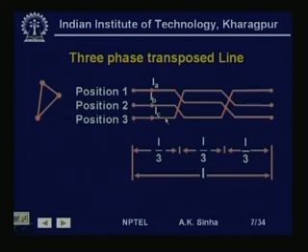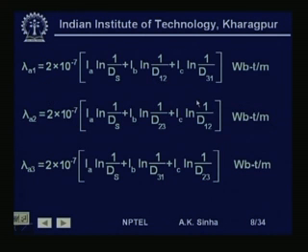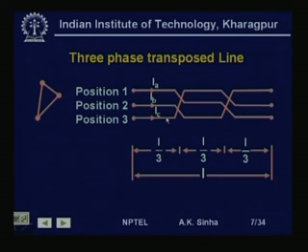If we see here, I B is now in this position, I A is in this position, the distance between these two is d 2 3, plus I C log n 1 by d 1 2. Again, I C is flowing in this and I A is flowing in this. So, the distance between them is d 1 2.